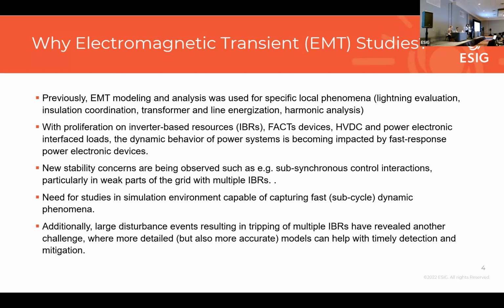The dynamic behavior of a power system is becoming impacted by the fast response of these resources. And we are starting to see new stability phenomena on the grid, such as subsynchronous control interactions between different power electronic sources. So we need studies and a simulation environment that is capable of capturing this fast subcycle dynamic phenomena.